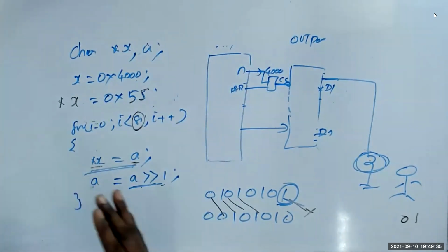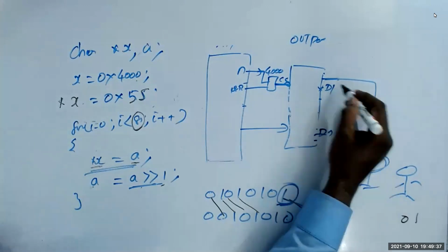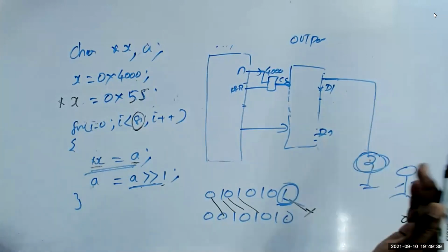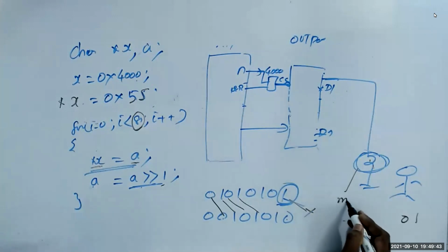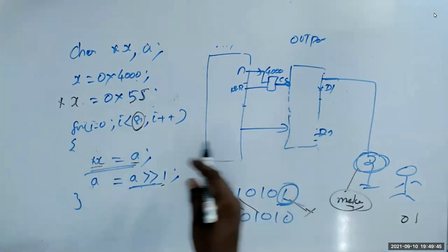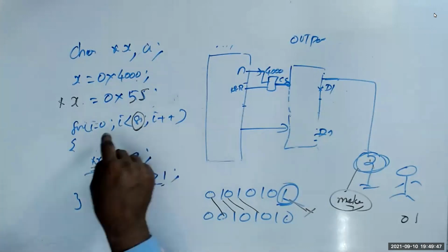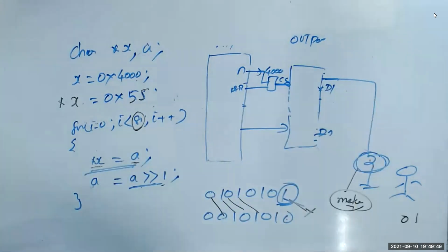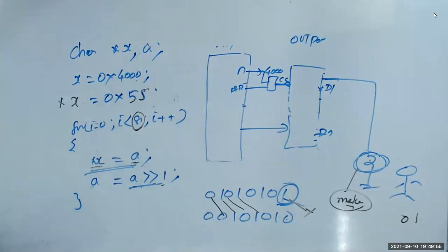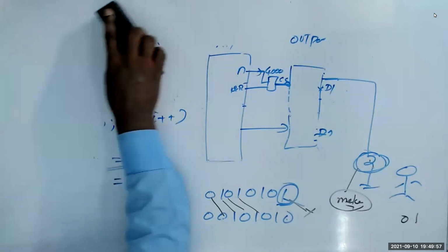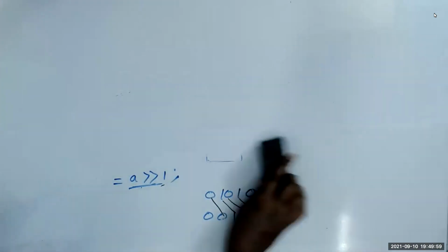So this is a trick, but the advantage is, let us say this guy is sitting a few hundred meters away. I need only one cable, man. If I do an 8-bit, 8 bulbs, I need to run 8 wires. People will say that it will be slow, man. Run only 1 wire. That is what is done today. There are a lot more reasons. As somebody has asked, why are we preferring serial?